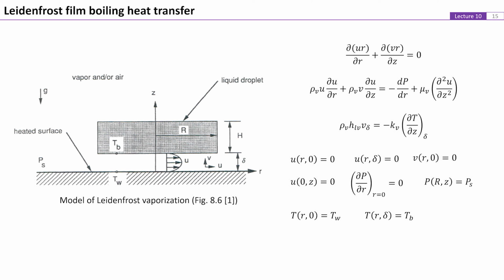There are two important issues regarding the Leidenfrost phenomena. The first one is the threshold minimum superheated surface temperature, or the minimum heat flux, at which the droplet is supported stably with the vapor that undergoes continuous film boiling. The second one of interest is the heat transfer rate under this condition.